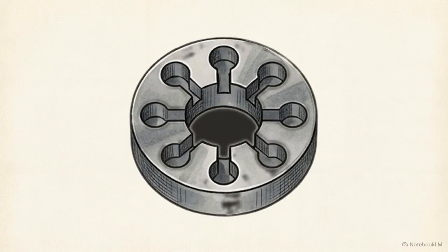This animated cross-section shows the internal geometry of a magnetron, a specialized bipolar vacuum tube. At its center is a heated cylindrical cathode, which boils off electrons. These negatively charged particles naturally attempt to travel outward in a straight line toward the positively charged circular anode block, which contains hollow slotted cavities.